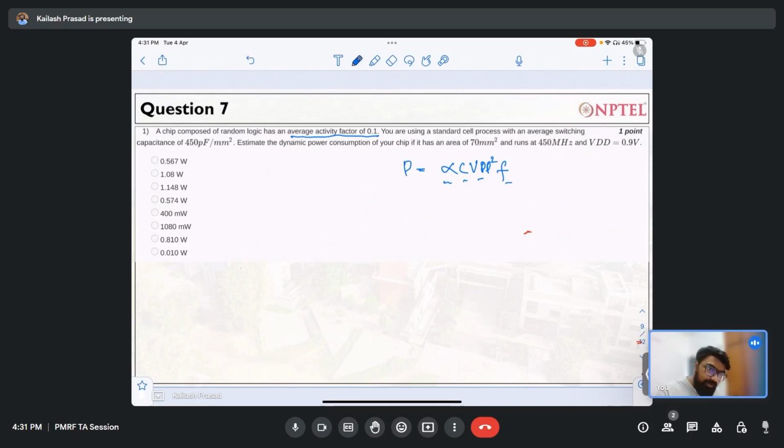So more current will flow, more power consumption will be there, right? So that's the second point, about capacitor. The third point is the VDD, right? The current is actually directly proportional to the square of the VDD. I equals mu N Cox W by L (VGS minus VTH) whole square, right? So if your VDD changes, current changes in the square, and that's the reason power also changes in terms of square. So VDD becomes extremely crucial while talking about dynamic power.